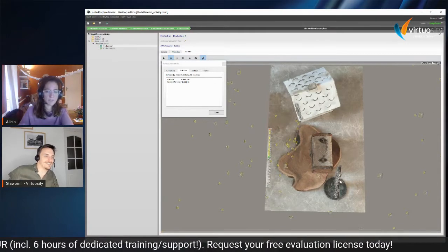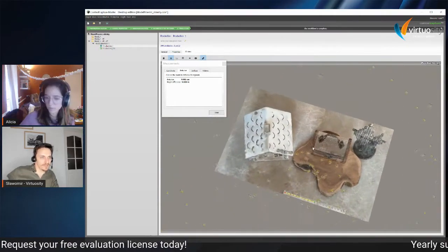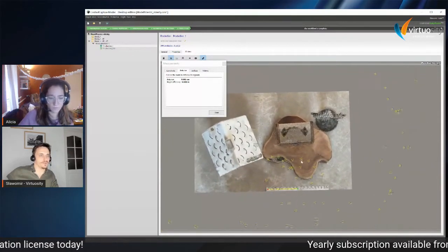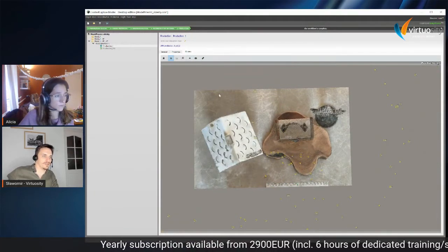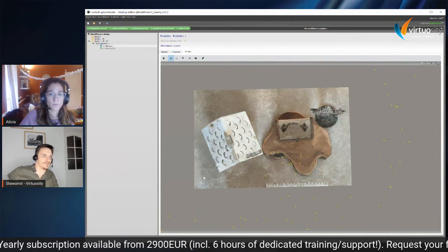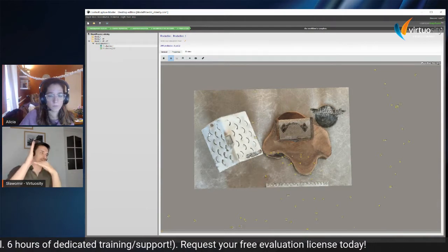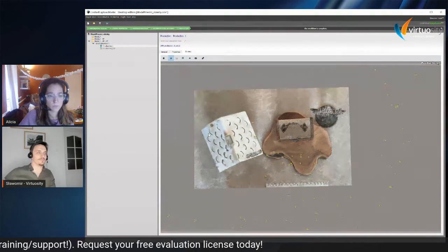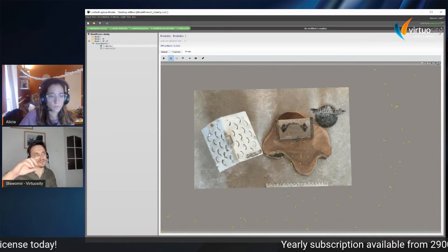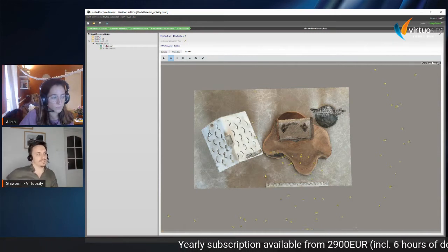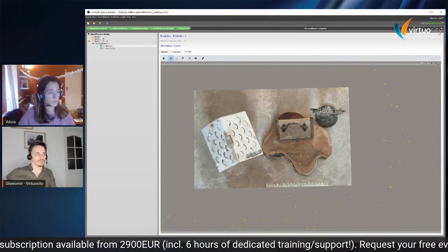Explain this again, I didn't get this. It's all about if we are distributing control points on our data, we have to keep in mind that when we are distributing them around, we can get much better accuracy, because then we can scale using two axes, so x-axis and y-axis. We can scale and fit perfectly to the points around. When we are just scaling in one direction, the different axes which are not related to the first one can bring worse accuracy, so we have to keep that in mind.